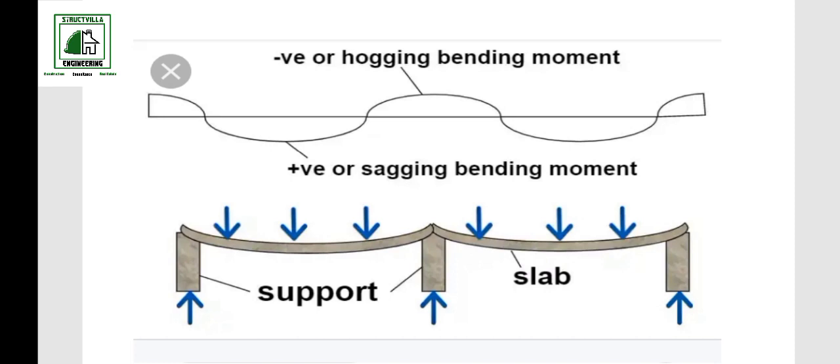The moment comes and then moves to the midpoint of the beam or slab, and because of a column, you are going to have that fixed end moment in the middle again. See, there's a rise in moments there, and then it came down, and then fixed end moment at the other end, right? So I told you, where do we lap our reinforcement?